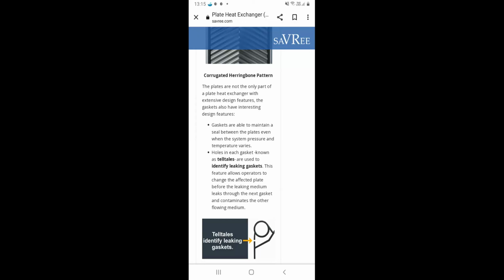But the surveyor won't say that it's okay. For working purposes, if you don't have any other option, you can put it in temporarily. But near the survey, don't say that you are using a Teflon plug or a wooden plug. Normally they say first, whatever the manufacturer's instruction is, as per the material of the tube, according to that we are using steel or brass.